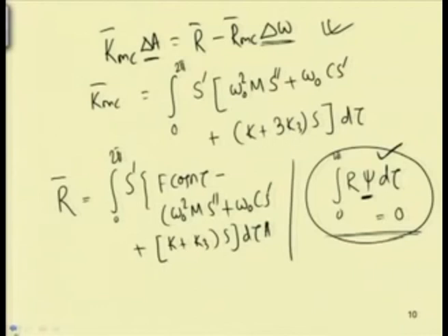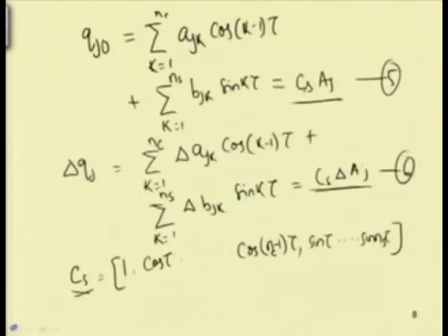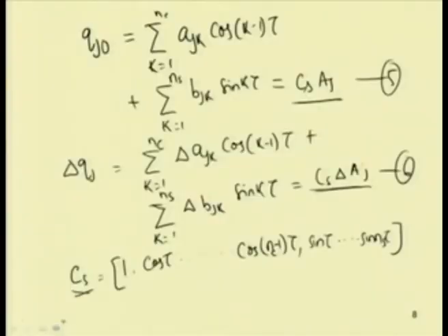So, in case of this incremental harmonic balance method, one follows two steps. In the first step, one takes the state vector and then increments it, and after getting the incremental equation, one applies the harmonic balance method using the Galerkin method. So, it reduces to a set of algebraic equations which are solved iteratively by using the Newton-Raphson method.